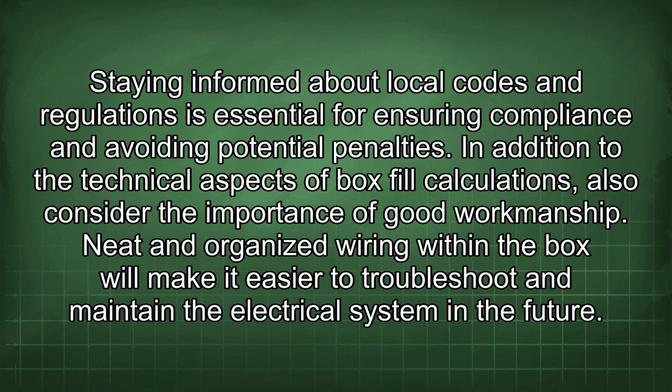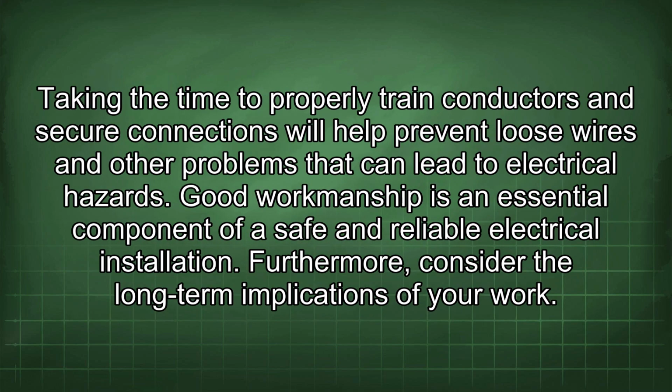In addition to the technical aspects of box fill calculations, also consider the importance of good workmanship. Neat and organized wiring within the box will make it easier to troubleshoot and maintain the electrical system in the future. Taking the time to properly train conductors and secure connections will help prevent loose wires and other problems that can lead to electrical hazards. Good workmanship is an essential component of a safe and reliable electrical installation.